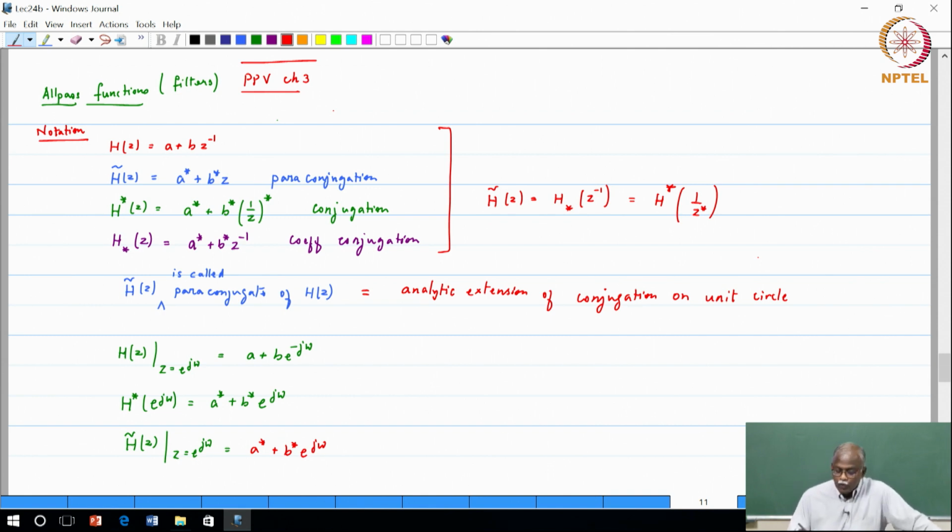Okay, so one of the things that we are often interested in, in the design of filters, once we start trying to impose these magnitude constraints, is magnitude H(e^{jω}) squared, and this can be written as H of z, H tilde of z, with z = e^{jω}.